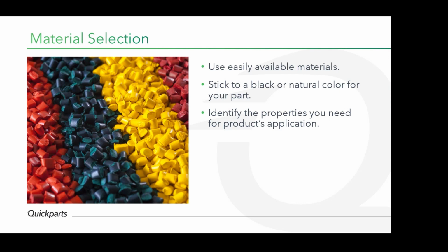For example, enclosures, right? Typically they are made of PC/ABS or ABS, so use those materials. They're typically used for that application, easily available, cheaper, and easier to process also. So choose materials that are easily available. You may take help of a material supplier who can guide you based on your function, so that you choose the right material that is available immediately, instead of waiting for 2 or 3 or 4 or 5 months at a very high cost. So make sure you use appropriate material.